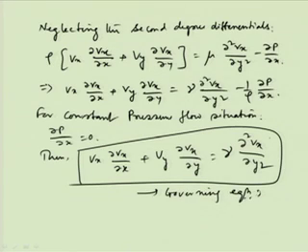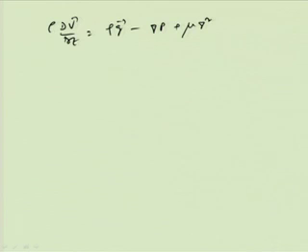It is similar to what we have studied in fluid mechanics, the Navier-Stokes equation, where in Cartesian coordinates for a two-dimensional system, for the x directional velocity, we will get exactly the same thing, okay, where gravity is neglected and all. If we write the Navier-Stokes equation, the vectorial form is rho dv by dt is equal to rho g minus grad p plus mu into grad square v. That is what for the x direction